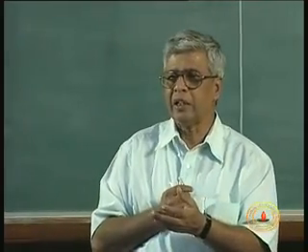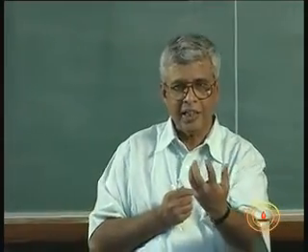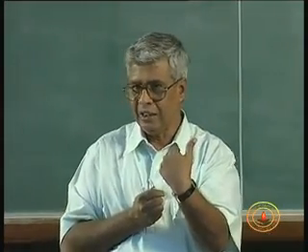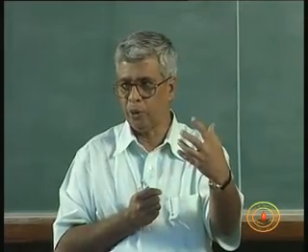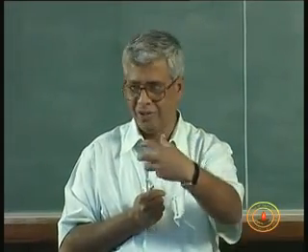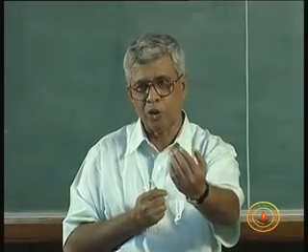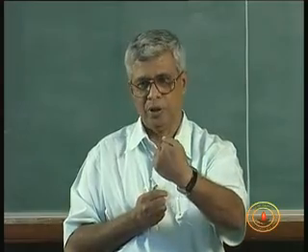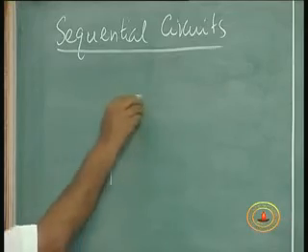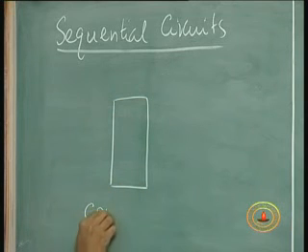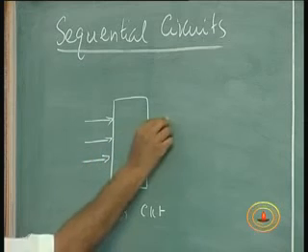So a sequential circuit will contain no doubt a combinational circuit, because once the history is given, it will consider that as one of the inputs. That's all, right? The combinational circuit takes the inputs and gives the output. Based on the input, it produces the output. Now the input is one more or many more depending on the previous output. So the previous outputs are also given as inputs. So if this was a combinational circuit model, we give inputs and it gives outputs.